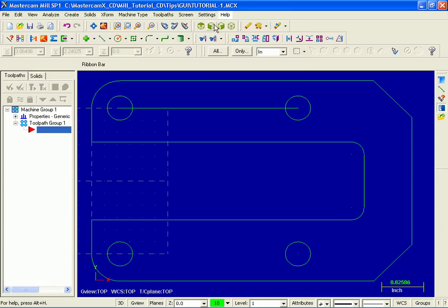Now down below we have a selection of toolbar icons, and if you cast your eyes over to the right hand side we have the MRU. Now MRU stands for most recently used toolbar, which presently is vertically docked. Now if I hover over this top icon, and you can see Customize, that was the last function that we were in, and down below Create Line Endpoint, that was the one prior to Customize, and then down below that Analyze Distance. So this is the MRU, most recently used toolbar.